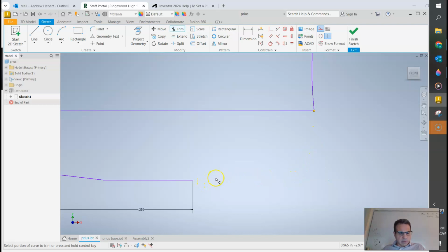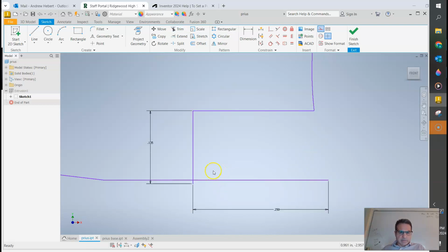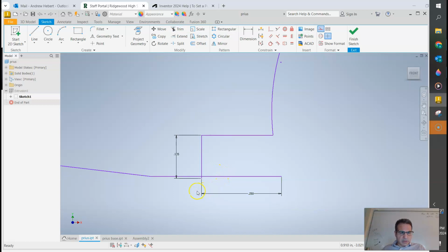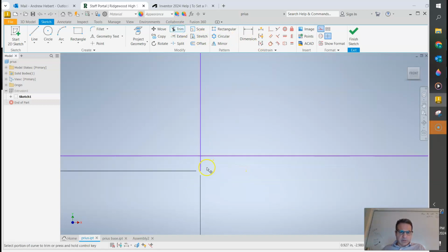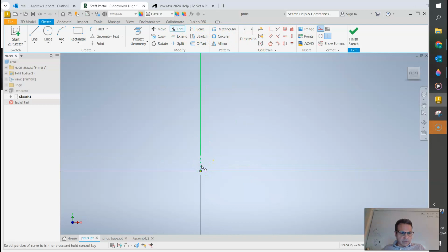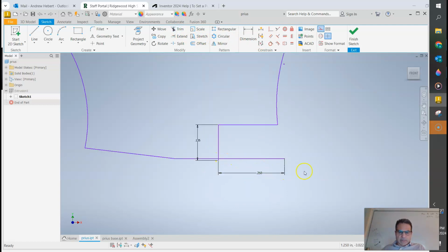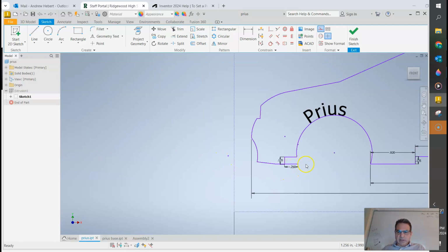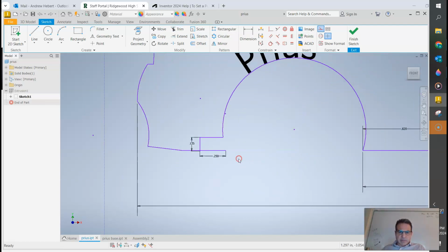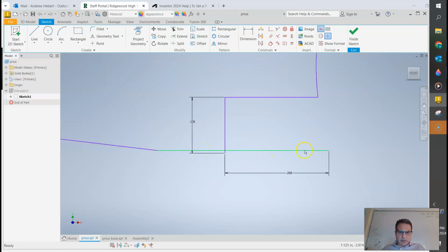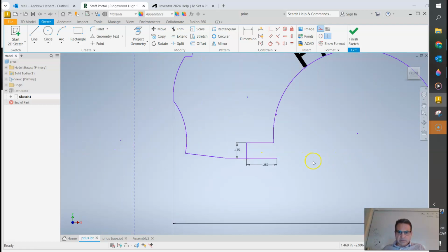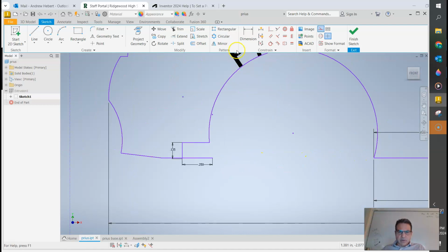And that got real goofy, Control Z. So when it trimmed right there, it got rid of, oh, it's because I lost that dimension. So I need this corner right here to be constrained to this corner down here. So let's go back to our constraints, horizontal constraint.